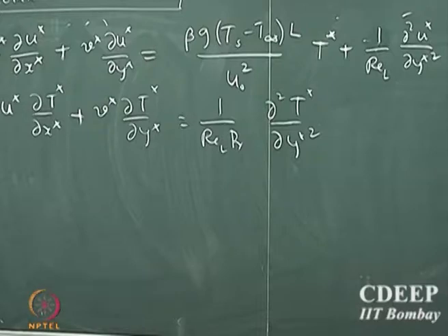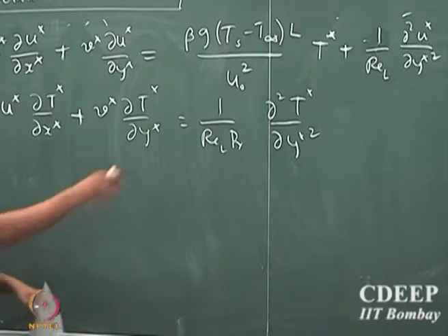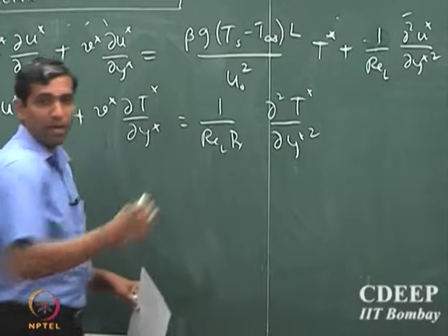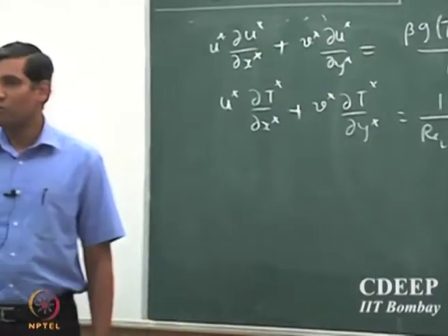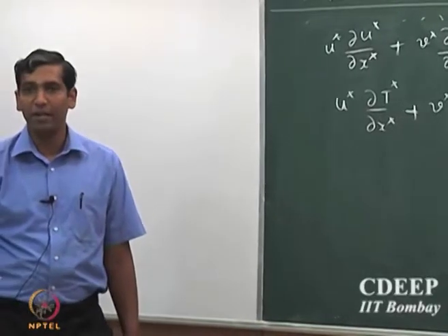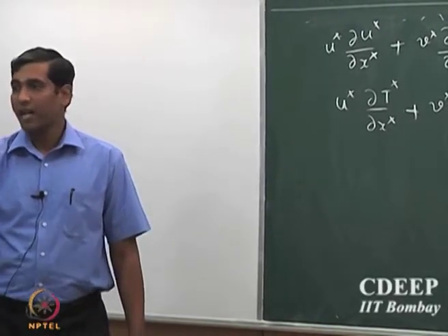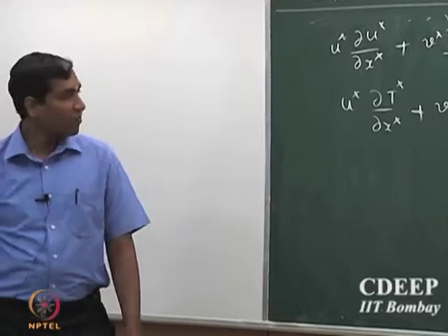They are not very different from what we saw in forced convection, except that you've got this new dependence of the velocity on the local temperature, and that's because of the density gradients, and that's because of the body force that we have included in the model equation. So now they are coupled. In the earlier case, the momentum balance and the concentration and temperature equations were decoupled. So we could solve the velocity profile independently with respect to the temperature. We can't do that here.